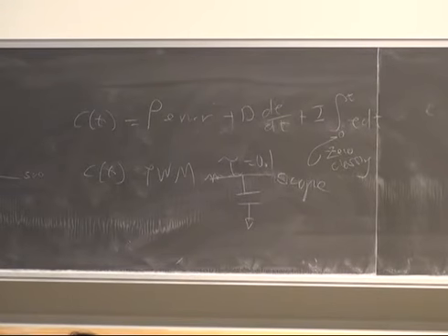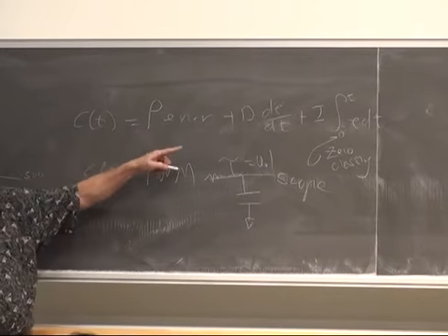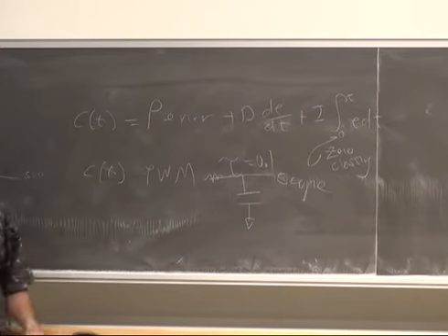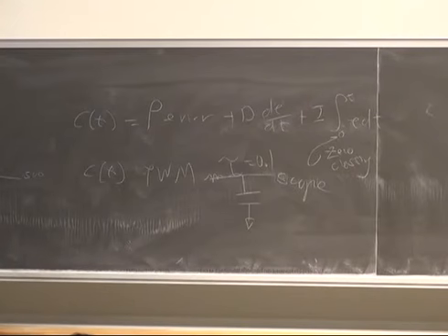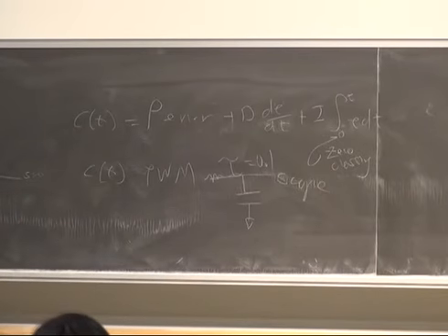And you need then to scale C of t to use that dynamic range. So there's going to be some fiddling with scale parameters here because you're going to be setting probably the scale through P, D, and I. The error is going to have some units, revolutions per second, revolutions per minute. Those are numerically different. That's going to change the numerical value of P. But you're going to have to play with that and figure out what works.